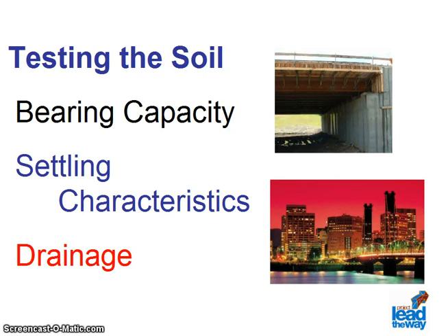Soil testing allows the engineer to classify the soil and to determine how the soil will behave as a construction material. Soil classifications determine the various physical properties of the soil and provides a correlation to the engineering properties. The soils underneath a building or commercial structure will influence the type and size of the structure foundation. Soil conditions can also affect the construction costs, especially if it is determined that additional materials or reinforcements are needed to ensure the integrity of the structure.